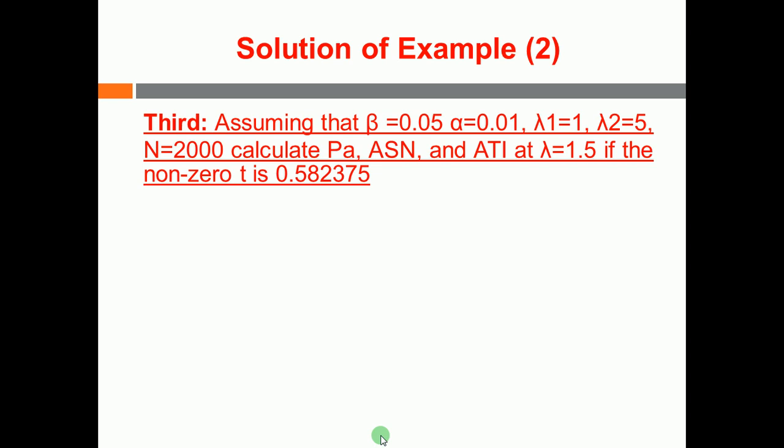Here lambda equal to 1.5 means that I am receiving lots which on average have 1.5 defects per item. Exactly like the class example we import, where on average each piece of glass has 1.5 defects. So it is equivalent to P, the percent of defective items.